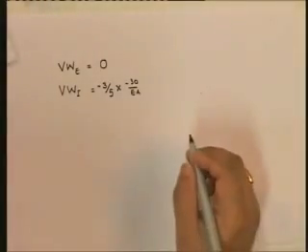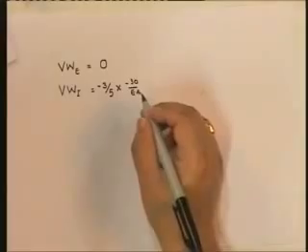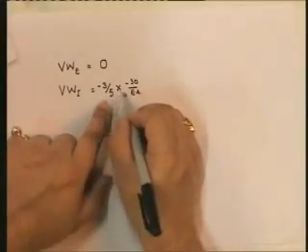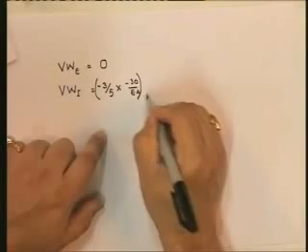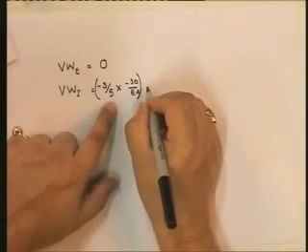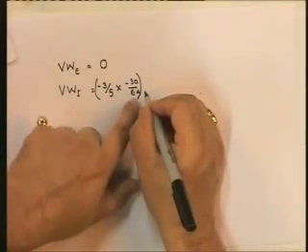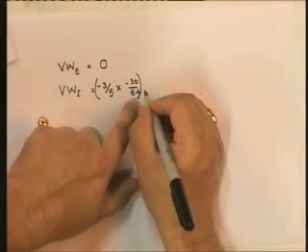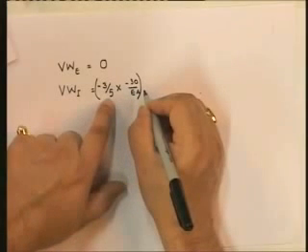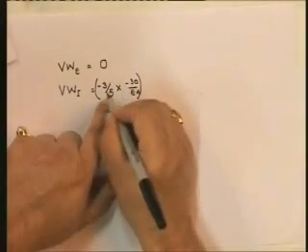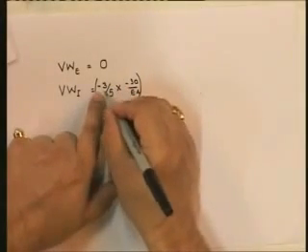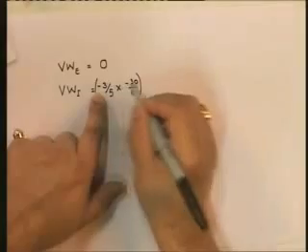So the internal virtual work contribution by AB is minus 3 by 5 into minus 30 by EA. That's the virtual work done by the real deformation in AB undergoing the virtual force in the system. This negative implies that there is a shortening, and a compressive force.